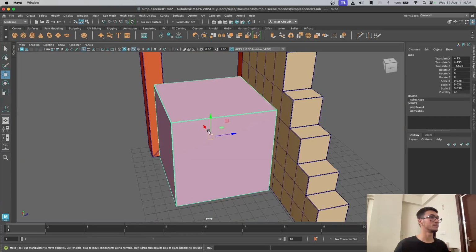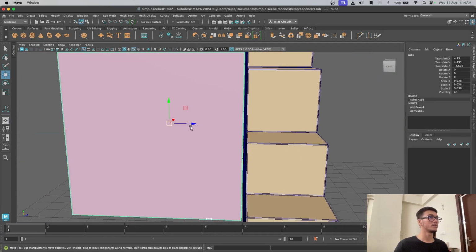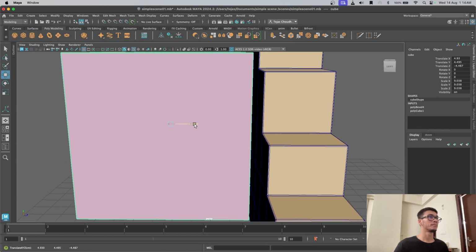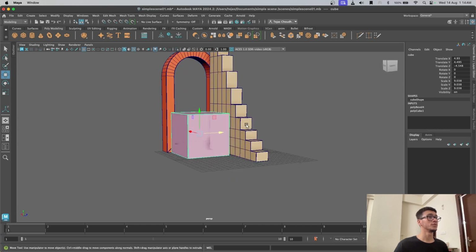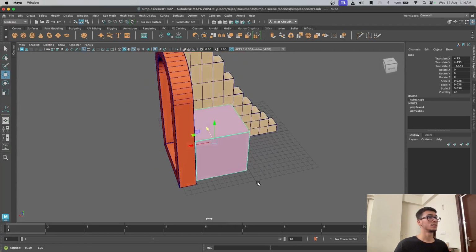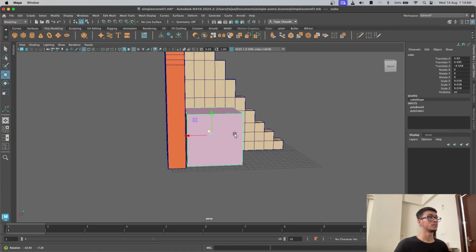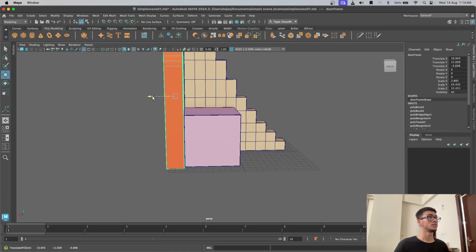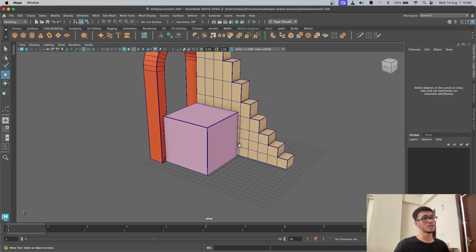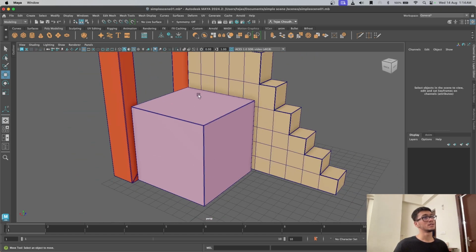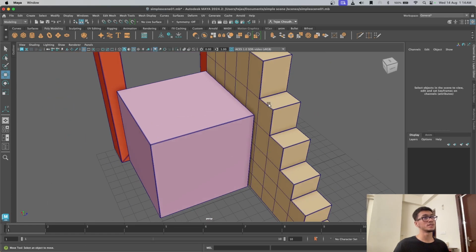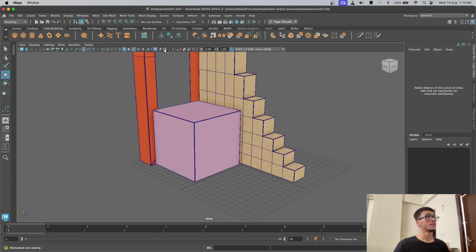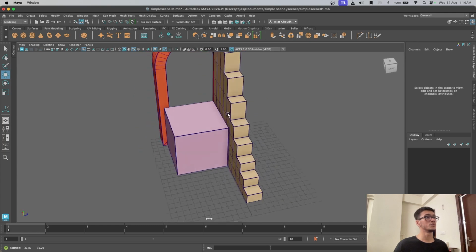Now we can have it closer to this wall, like this. You can turn on this ambient occlusion so you can see shadows. It's like fine, subtle shadows, like a light darkish area here. It shows it's very close to this. It shows contact points. And if I turn on anti-aliasing, it will become smooth.